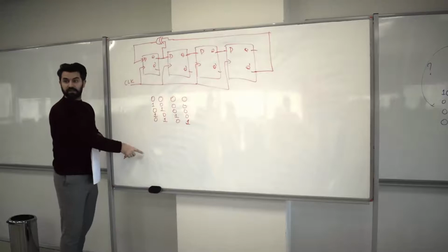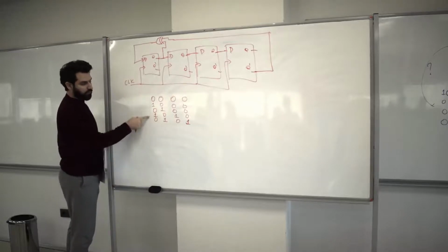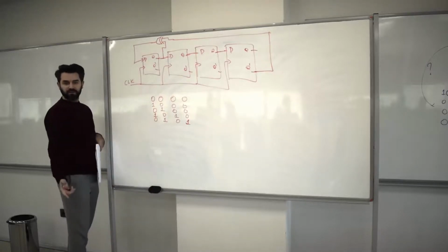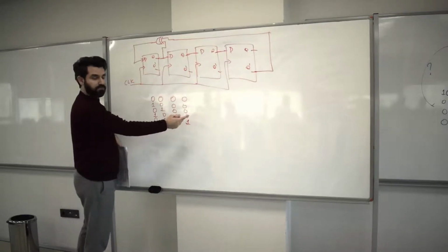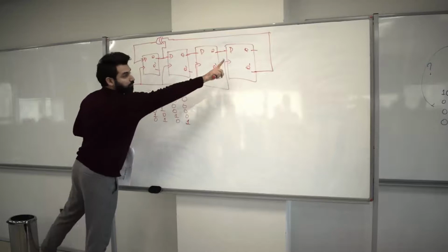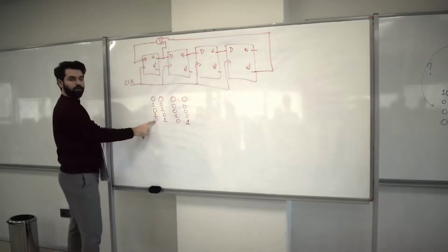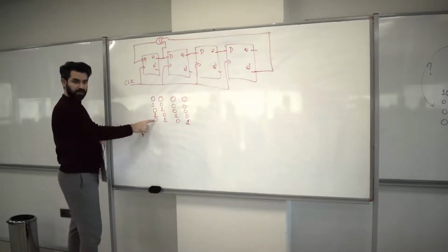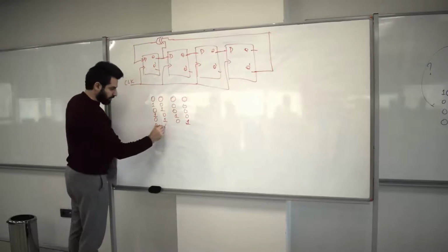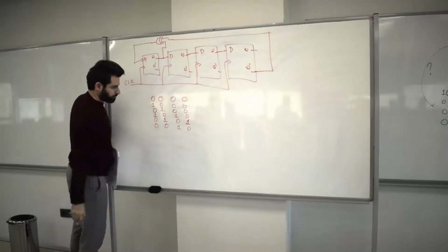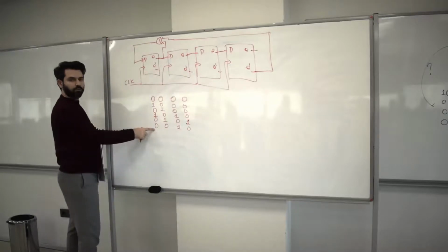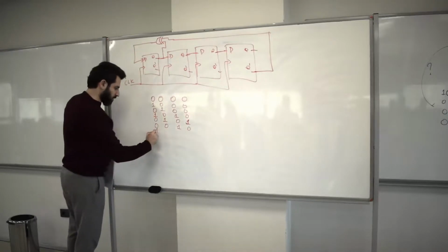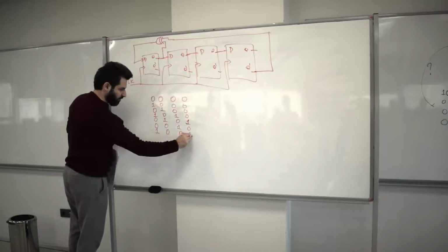I continue doing this because I haven't hit one of the previous sequences yet. Now this is 1, and this becomes 0 because I took the output from Q prime, remember? That's 0 and that's 0 XORed to generate the next state of the first flip-flop, which is 0. 0, 1, 0. And then this becomes 1, this is 0. XOR them, 1. You get 1, 0, 0, 1.